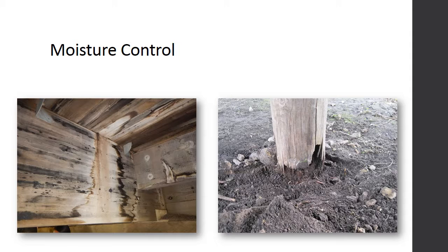Since it is highly unlikely abutment and pile locations will be moved on existing bridges, it is paramount to take note of particular piles that are apt to see the wet and dry cycling so that special attention may be paid to these piles.